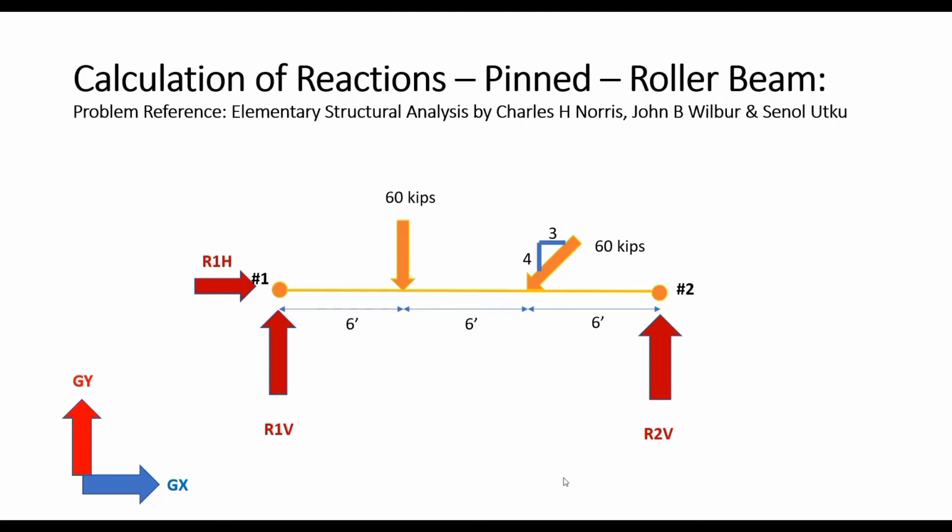Now, this representation of the structure that we see on the screen, where the support representation has been removed and has been replaced with the restraining force that those supports provide, is called a free body diagram. A free body diagram is a representation of the whole structure or the part of a structure where it is only represented with its applied loads and the reactive loads on it. So free body diagram is a very important concept which we will use consistently as we go along.